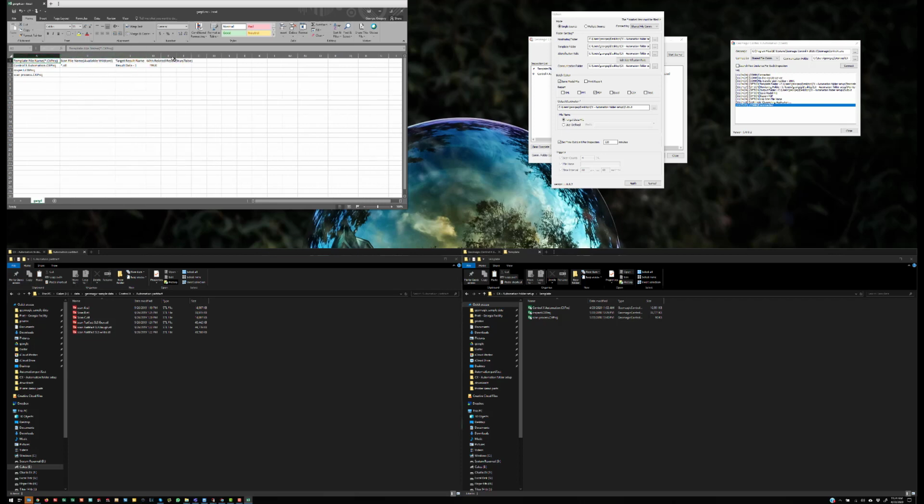You can establish rules here. So you can build a library of parts. So if I wanted like 13 different part numbers, what you can do is say any file with part number XYZ123 dot star, measure with this file here, right? And then within that file, you can tell it what to do. Use result number 1, 2, even run scripts using our scan processes. And then this is whether it's going to report or not.